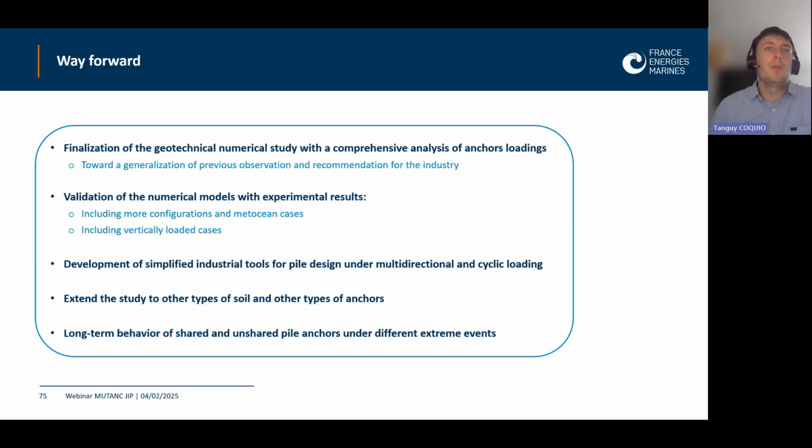The validation of the numerical models with experimental results should include more configurations and metocean cases, and also include vertically loaded cases, because at the moment only horizontal loading was validated with the numerical model. Also, we can think about the development of simplified industrial tools for pile design under multidirectional cyclic loading, extend the study to other types of soil and other types of anchors, such as, for example, clays or suction anchors, and look at long-term behavior of shared anchors under different extreme events.